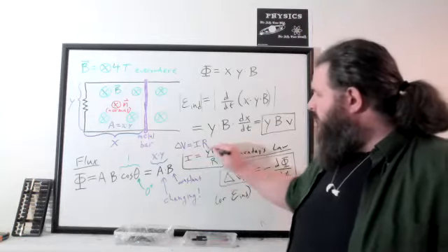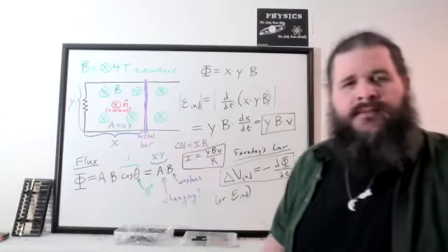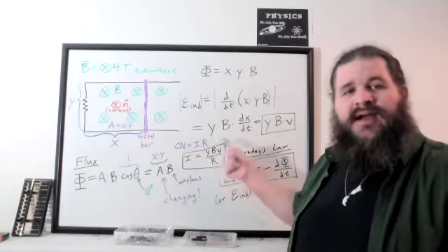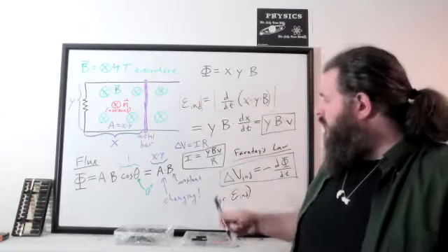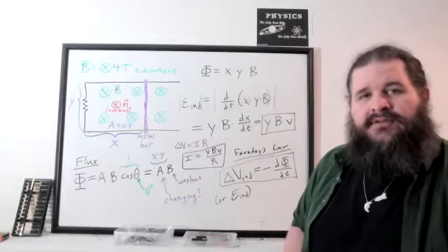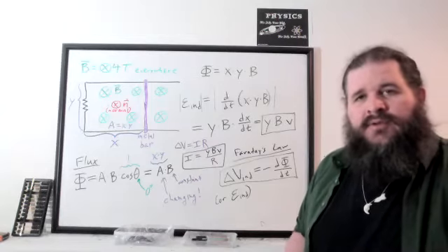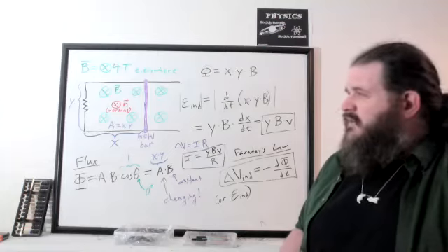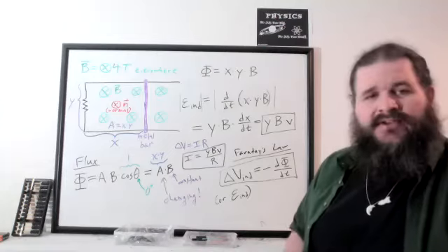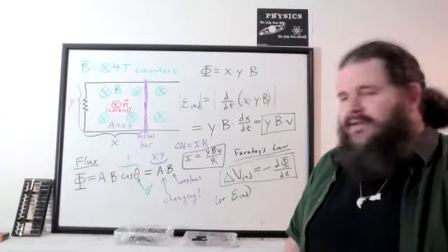So the current that we should expect to flow through this loop is distance between the wires times the magnetic field strength times how fast the bar is being moved, divided by the resistance. That'll tell us the current through that resistor, which we can assume will give us information about how bright the light bulb is, if it's a light bulb, or how loud it is, if it's a buzzer. Any questions on that so far?